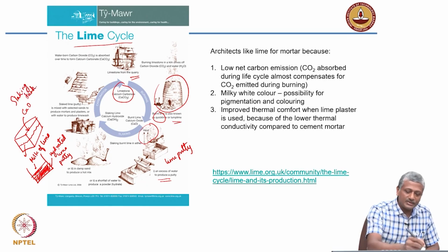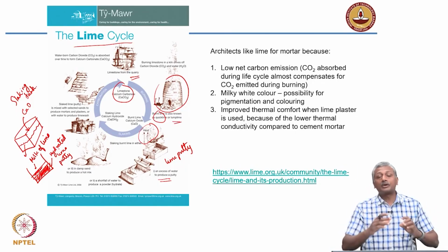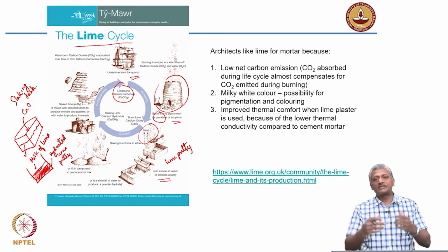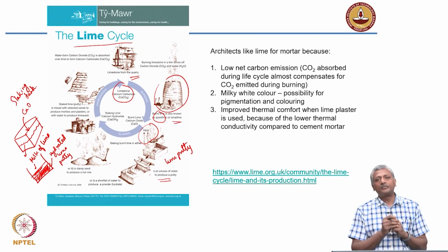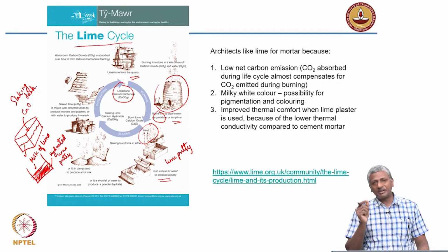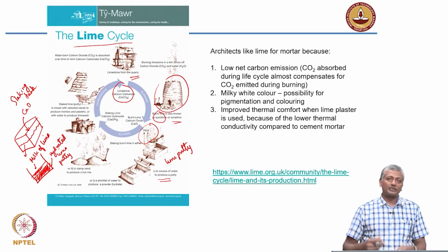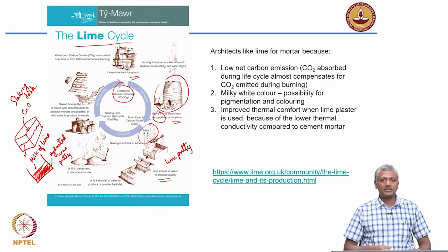Now interestingly, what has also been found is that the prolonged exposure of this lime inside the slaking tank results in very different qualities of the lime that you get for mortar making. Generally they say for plastering purposes, when you want a very fine texture, the lime has to be slaked for a long time, nearly 6 months sometimes. For binding of blocks together, the lime mortar does not need that kind of texture. So there you can slake for 1 to 3 months itself.